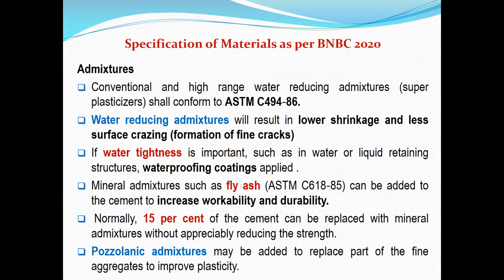In terms of admixtures, conventional and high-range water reducing admixtures like superplasticizers are used, and they shall conform to ASTM C494/C494M. In the case of water reducing admixtures, they will result in lower shrinkage and less surface crazing, the formation of fine cracks. What happens? You can use water, no problem.